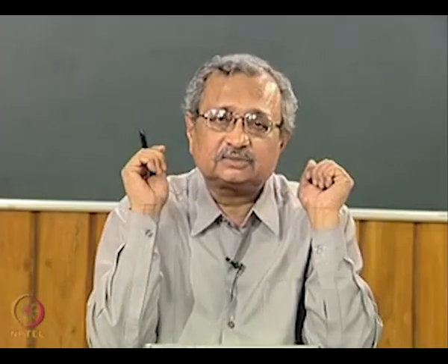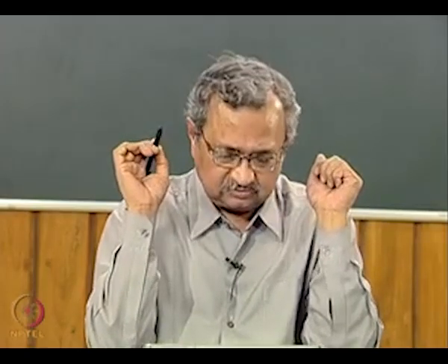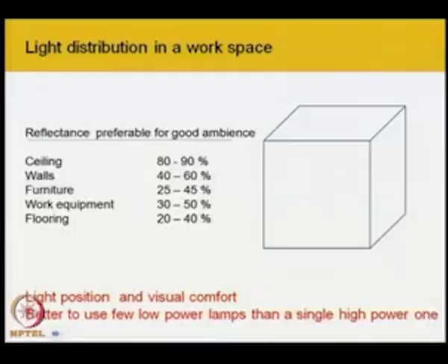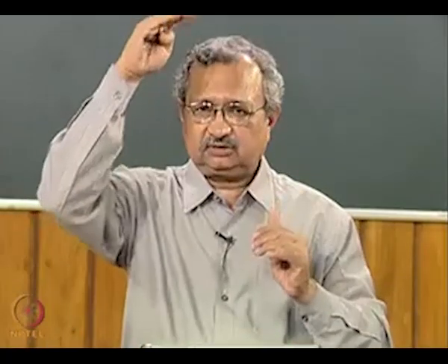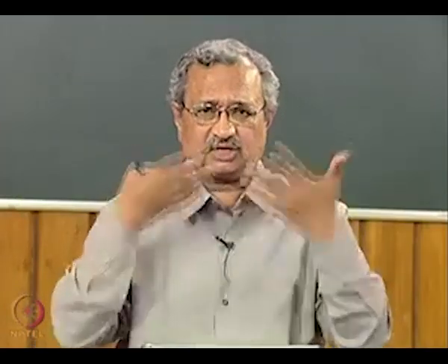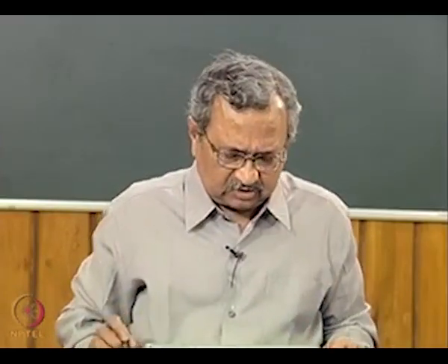Now, another thing comes: light distribution in a workplace. In a specific space where you are working, whatever light intensity is required to perform a task, from the ceiling, walls, floor, furniture and the object of interest, how much light should reflect to me to have a balanced ambience? It is seen that each and every color also has a specific reflectance value.